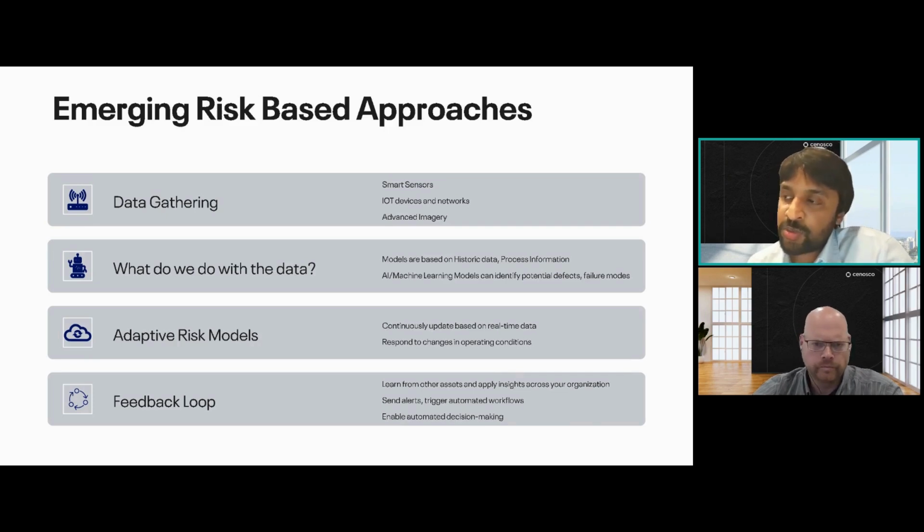That analysis will typically identify your corrosion rates. We will of course look at historical results and identify long-term corrosion rate, short-term corrosion rate, and average corrosion rates, and then come up with due dates for inspections accordingly as well. So this is the conventional way of data gathering: a manual way of performing inspections, gathering data, analyzing the data, and using that data to drive decisions accordingly.